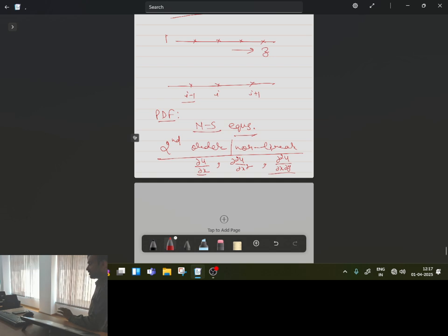Is this one clear? Now, whenever I will be considering the one-dimensional grid structure where variation is taking place only along a single direction, then using the Taylor series approximation, I have to calculate the value of any parameter u at point i plus 1, by considering that I am calculating this value with reference to point number i, and in between i and i plus 1 the distance is delta x.